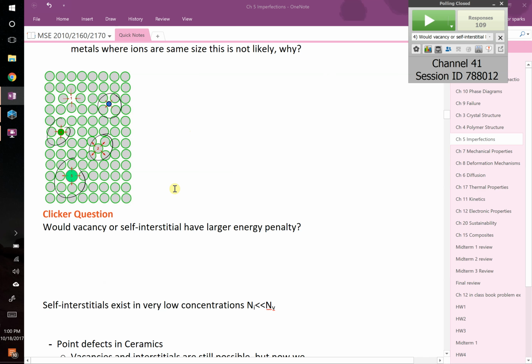Right? So clearly site number 1, let's change color. Site number 1 is a vacancy. That's where an atom should be, but it's missing. That's this one up here. You can have a self-interstitial, which is where an atom shouldn't normally be, but it's crammed in there. So where's that happening? That's number 3, this blue one. So that's our self-interstitial. Since you're talking about an atom fitting where it shouldn't be, self-interstitials tend to be smaller atoms. And the word self-interstitial actually means it's of the same type. So in a metal, technically 3 wouldn't be a self-interstitial, that would just be an interstitial.